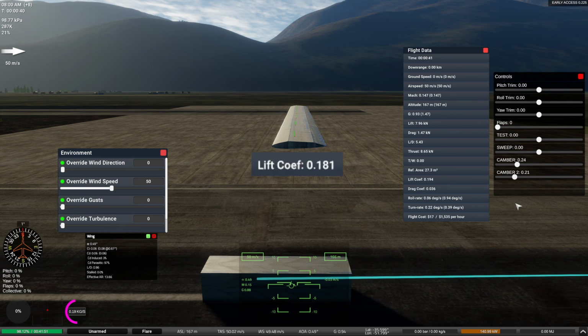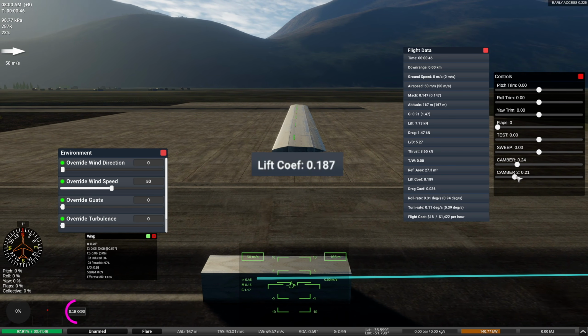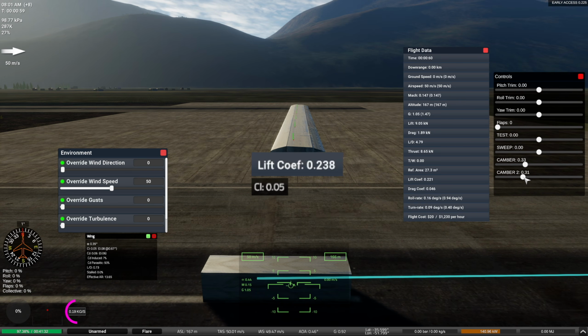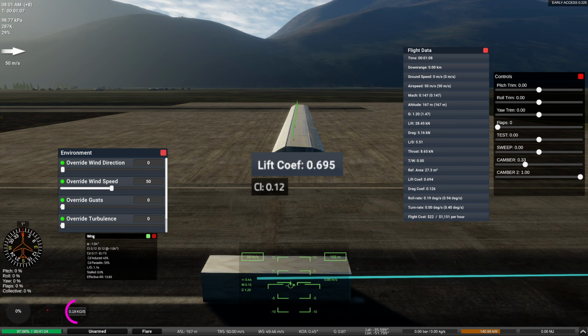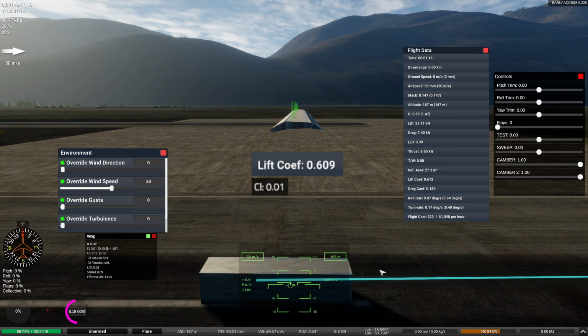As mentioned earlier, camber can be mimicked by giving the leading and trailing edges of the airfoil a default value and a response to any input, so long as the range values are equal so the edges do not move. In this video, I am using a slider input with variable range so that I may adjust the camber in real time. As I adjust the camber of this airfoil, note that the wing information window displays a very different lift coefficient than that of the flight window. As of version 0.225, the wing's information window only reflects the contribution of the main wing piece to the lift coefficient, and not the leading and trailing edges, while the flight window shows the overall lift coefficient of the aircraft, which is the entire wing in this case.